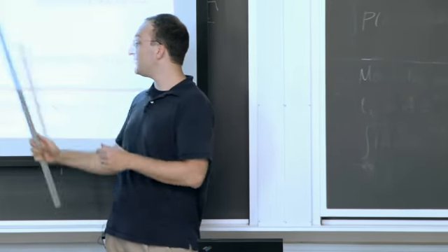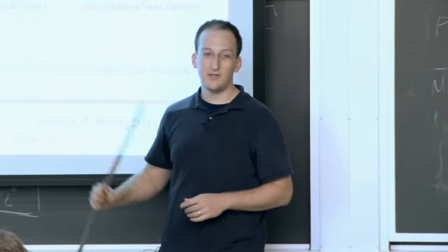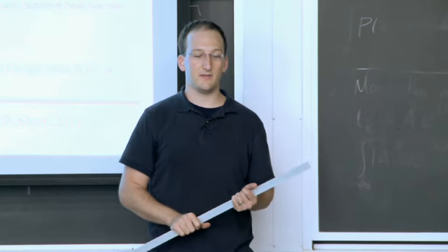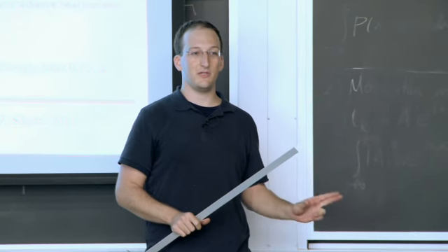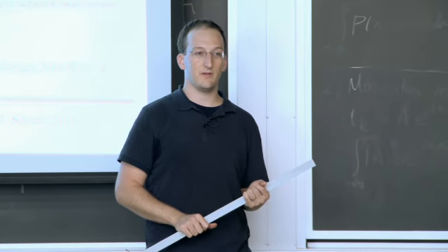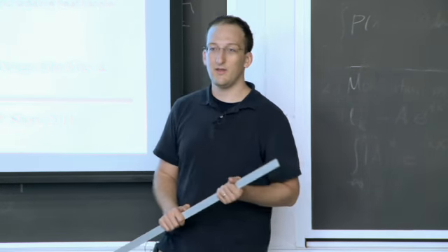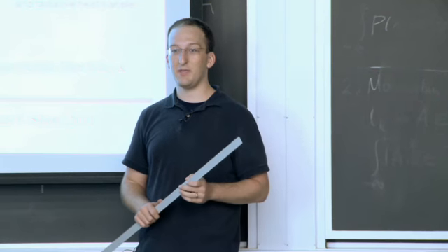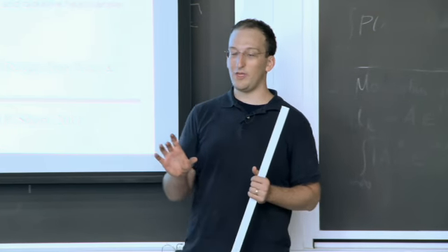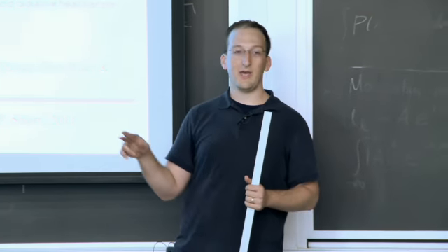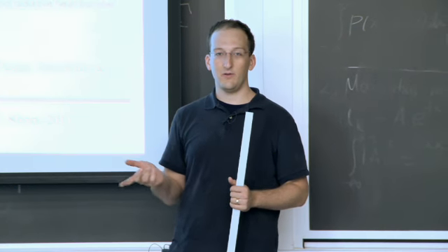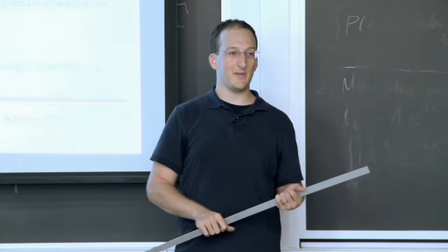It could be single phase on one side, 2 phase on the other. Where do you find these sorts of heat exchangers in a nuclear plant? So if you think about it, single phase on one side, 2 phase on the other. Steam generator. Yeah. So like a steam generator in a liquid lead plant or a sodium plant, you have only liquid on one side, you have liquid and gas on the other. And when you evaporate the gas, what's that type of heating called?